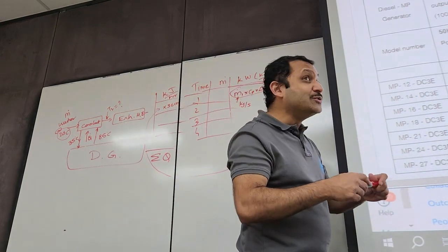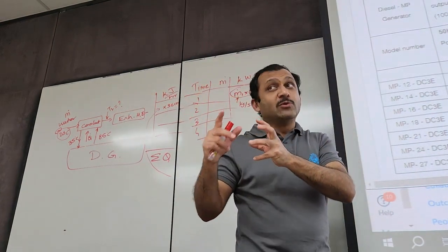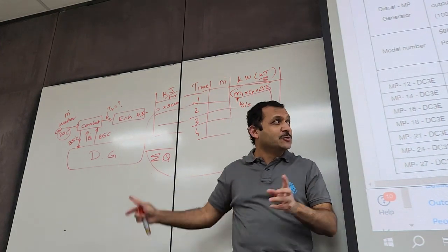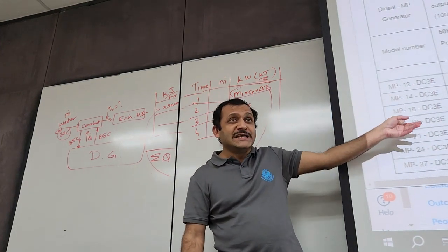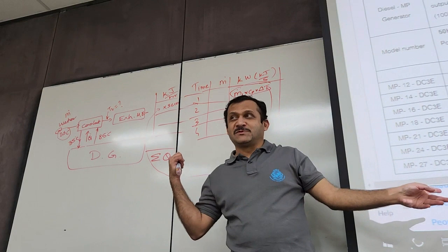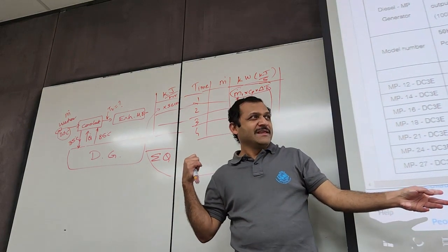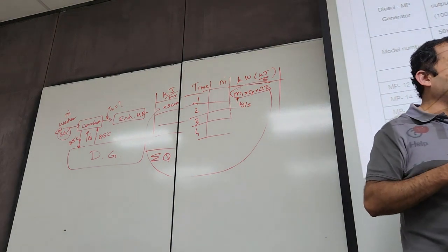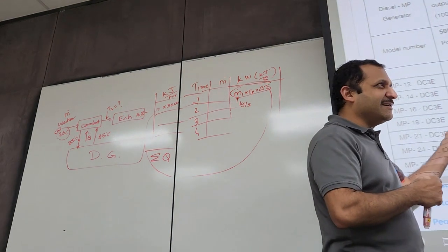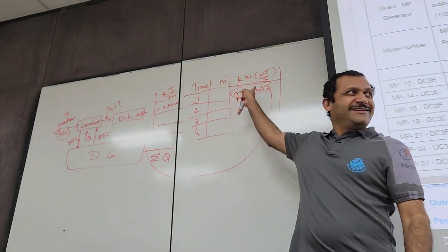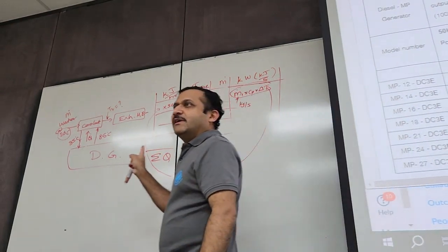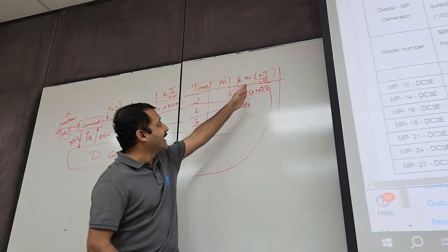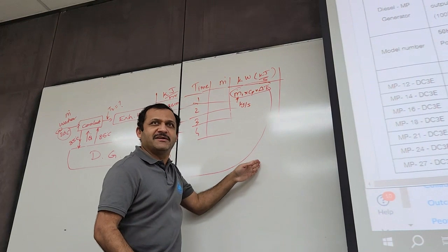Now, you will have to use that total amount of thermal energy to figure out if your diesel generator is capable of supplying thermal energy. One first initial step, I think that's what you might have done when selecting, you might have looked at your peak. A lot of times I've seen students looking at how many kilowatts, right, for every hour.